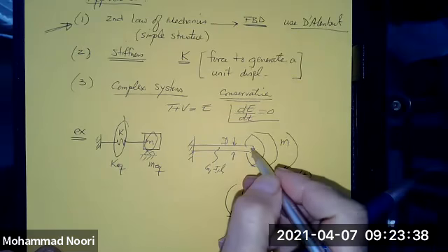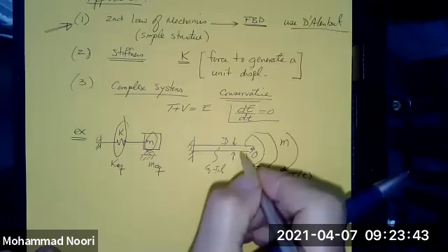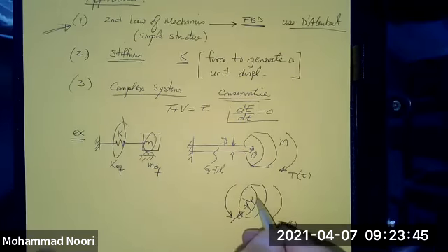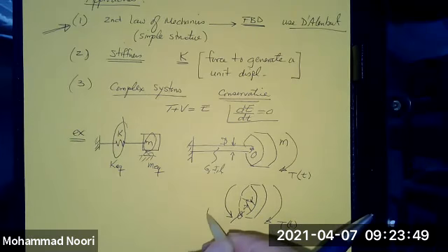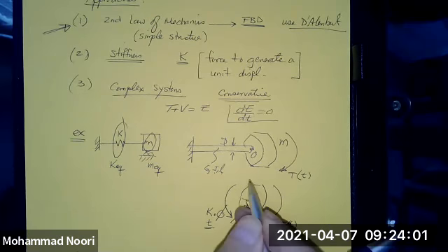If the shaft experiences a deformation phi, it is the deformation of the shaft that is resisting the motion of this disk. In other words, the shaft represents a torsional spring, which we will find, of course, resisting this rotation. So that is a force or moment that is resisting the motion.